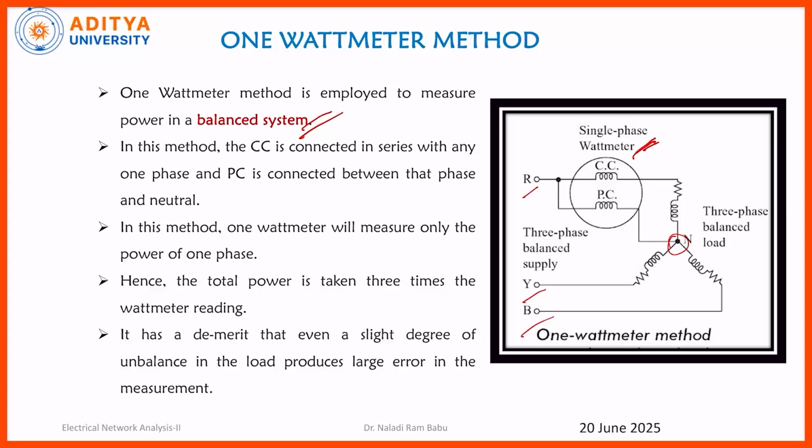As we have discussed earlier, the wattmeter consists of 4 terminals. They are named M, L, C, V, where M means mains, L means connected to load or line, C means common, and V is voltage. In almost all circuits, this MC will be in short circuit condition. M and L are called current coils, that means these are connected in series with the load or source, whereas C and V are called pressure coils. That means these are used to measure voltages across the load or the source depending upon the necessary condition.